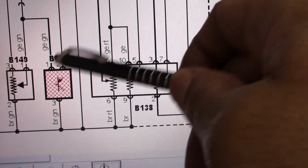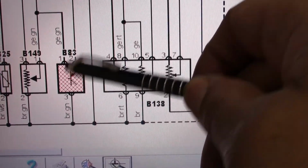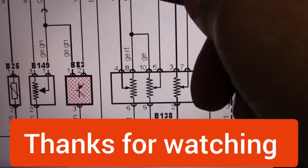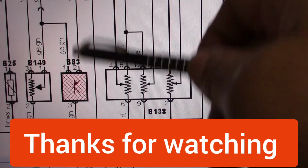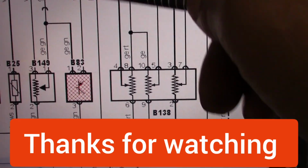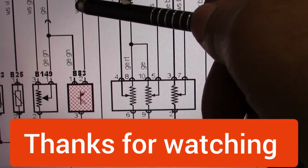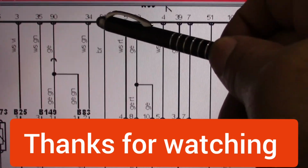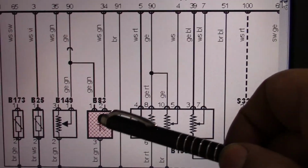If we don't have the map sensor output signal voltage here, then the problem is within the wiring harness between the ECU and the sensor.